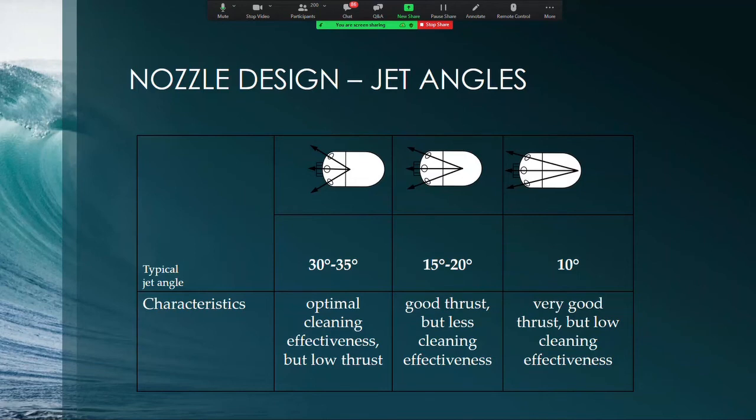While that does a good job, what I would look at as opposed to that kind of nozzle would be a nozzle with a controlled rotation head, and that would clean a full 360 and not leave stripes inside the pipe. It will basically hone and clean the inside of the pipe quite nicely, versus a nozzle that just pulls off where the water jet hits. Between the water jets, you'll end up with what I call stripes inside the pipe.